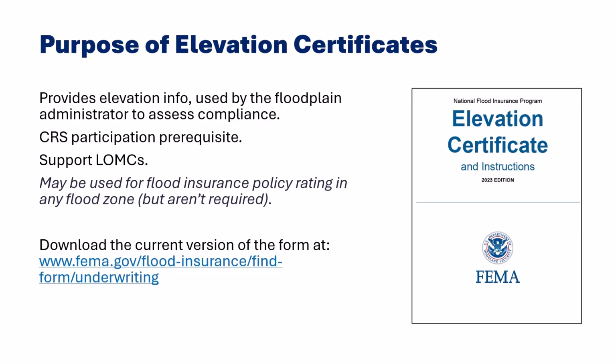The Elevation Certificate form, or EC form, is designed specifically to collect the elevation and BFE data that you as the floodplain administrator need in order to assess buildings' compliance. Information on the form can also be used to support letters of map change. And if your community is participating in the Community Rating System, or CRS program, use of this EC form is required to collect this elevation data.